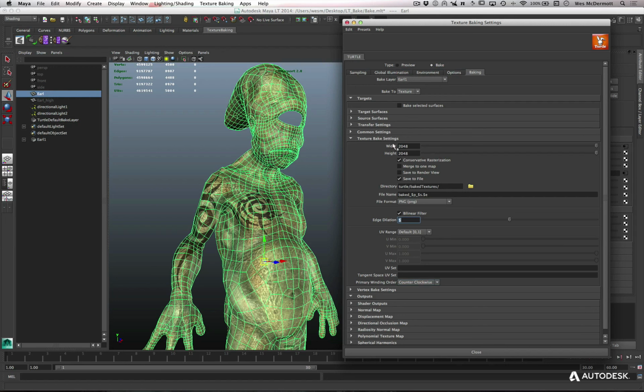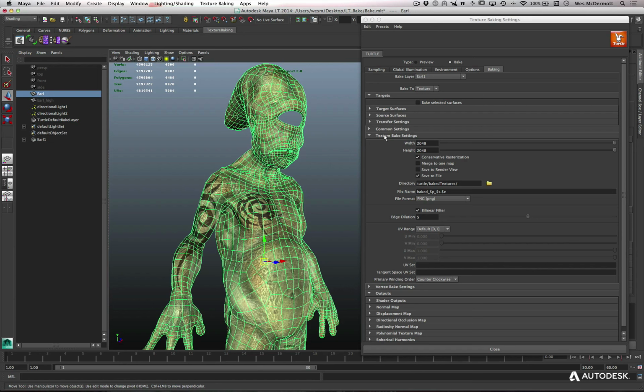So in a sense, in our bake set here we have multiple objects and some of those UVs are overlapping, especially, actually a better example would be if you had mirrored UVs. And so this can control how baking polygons with mirror UVs should be handled. You can control your winding order on this, and that can help with that situation. So now we'll go ahead and just bake our normal map.